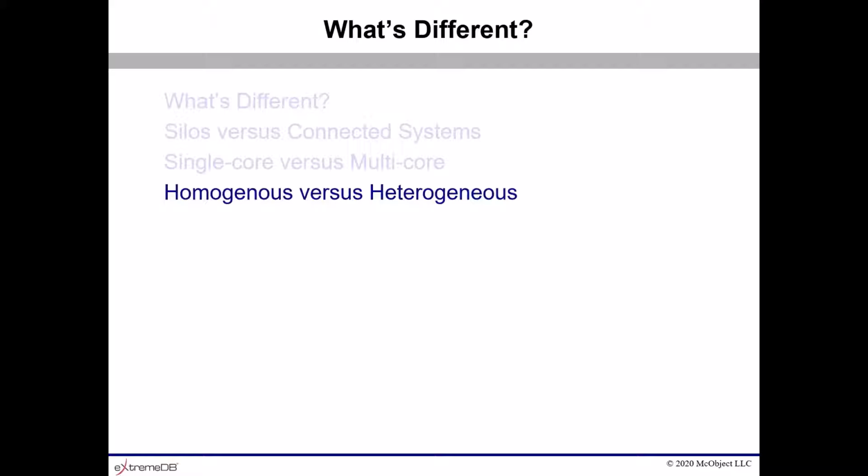Unlike desktop and servers, which are predominantly x86-based, embedded systems could use ARM, MIPS, PowerPC, Coldfire, Easy80, Tile64, and more processors. But the data didn't need to move between systems. So being able to build with different tool chains for different target platforms and operating systems was enough. In other words, the database system code needed to be portable, but the data didn't need to be portable.